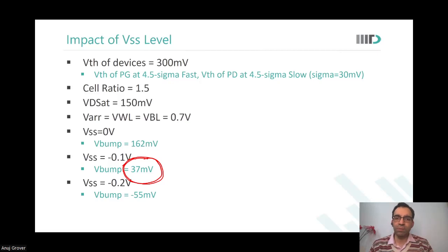0.3 volts, 50% higher. It went from 0.7 to 1, so in the same ratio the negative voltage would also increase. So now what is the voltage across the different devices? The voltage is 1.0 on the gate, let us say, and minus 0.3 on the source or drain. So across the gate oxide, the voltage now is 1.3 volts.